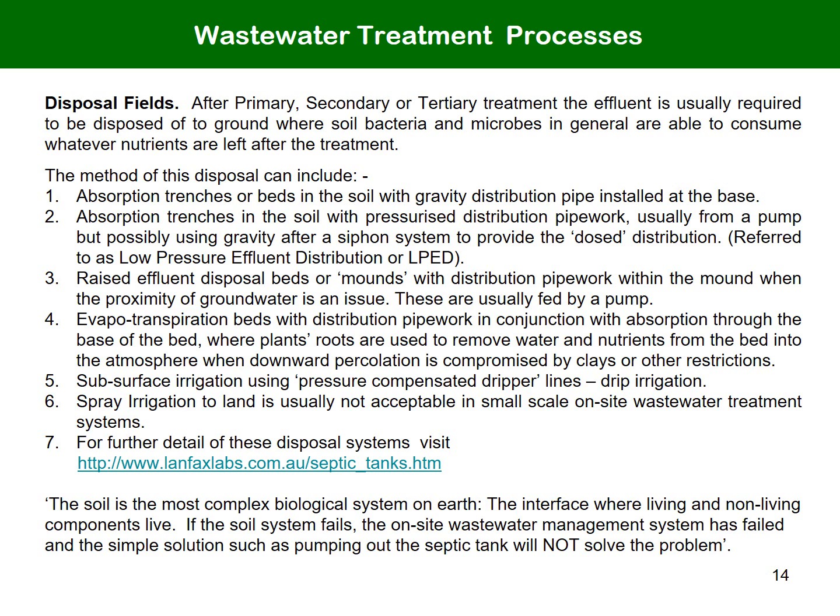After primary, secondary or tertiary treatment, the effluent is usually required to be disposed of to ground, where soil bacteria and microbes in general are able to consume whatever nutrients are left after the treatment. The method of this disposal can include trenches or beds in the soil, either gravity-fed or dosed with a pump or siphon. The pump or siphon systems are referred to as low-pressure effluent distribution, LPED systems, unless pressure compensating drippers are used, in which case more pressure is required in the dosing system.